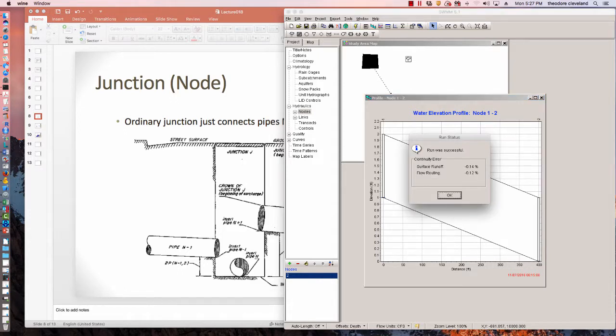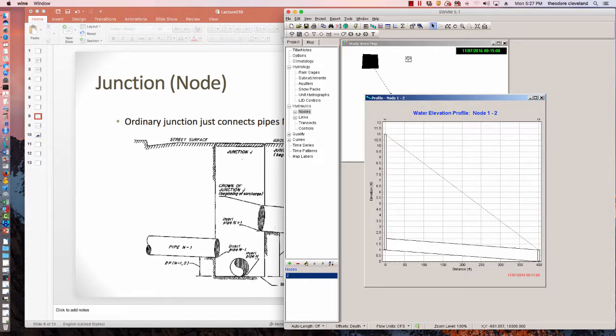We rerun the program and it should read, there we go. The max depth is the 1 plus the 10 to put the profile grade at 11, and then you can see the pipe height here, which is 1 foot, is shown. If you don't supply a max depth, it uses the larger diameter of whatever pipe connects to it.